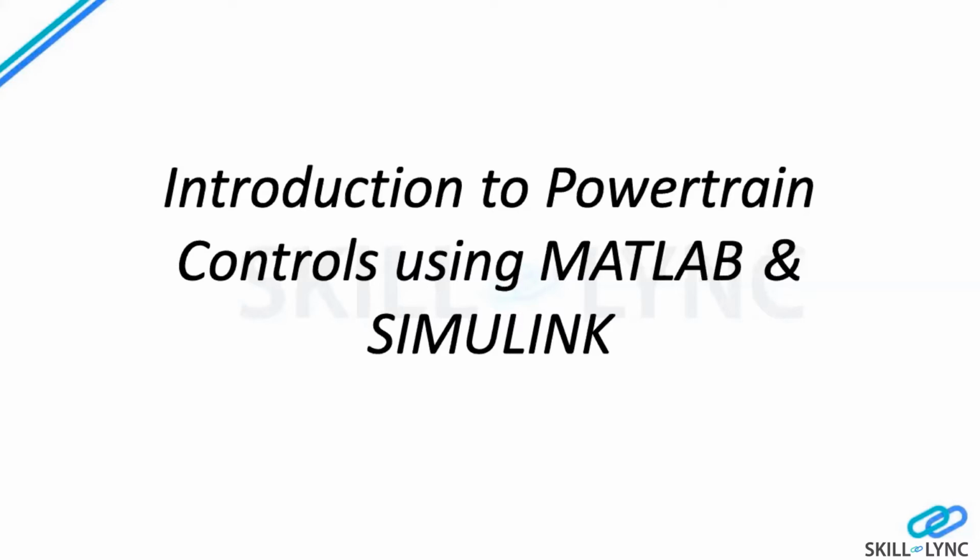So these are the requirements, and to develop the controllers, to take decisions, to build counters, timers, etc., we will be using a lot of very small but powerful blocks inside Simulink, like switches, unit delays, mux, demux, bus, etc. So here we have covered all those basic block sets in Simulink and how we can practically use them to build models.